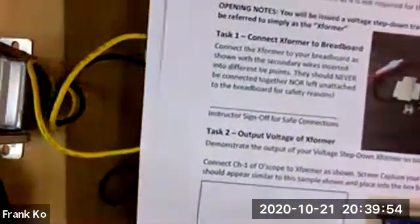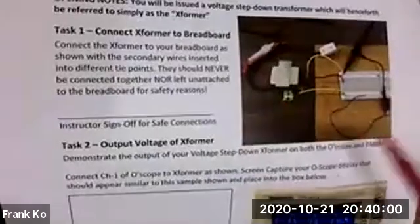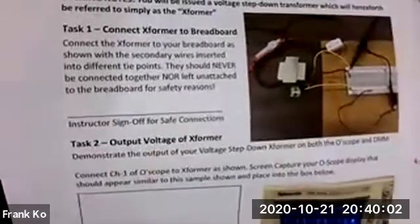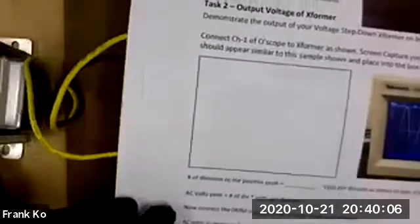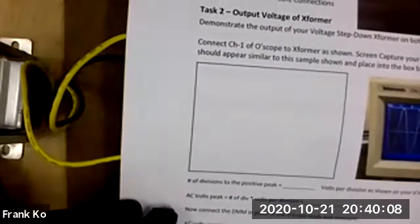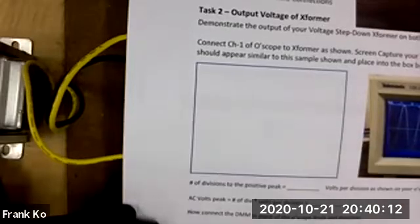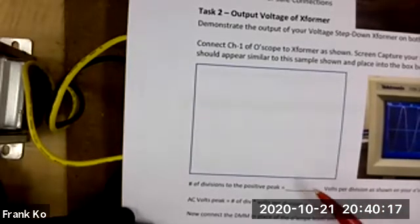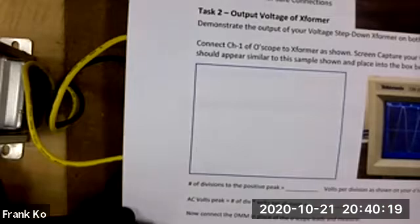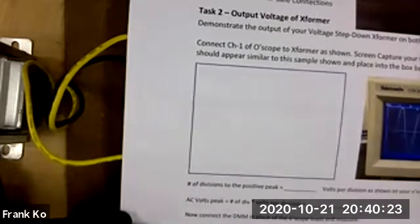All right, so on your handout, you have connected the transformer to the breadboard. That's been done successfully per the illustration. My sign off has been verbal, that's fine. And then the output voltage of the transformer, you were able to verify before. You can take your screenshot or take a cell phone picture. And you were able to determine by counting the number of divisions on your scope what the waveform is, or you could use your cursors, whatever is easy for you.